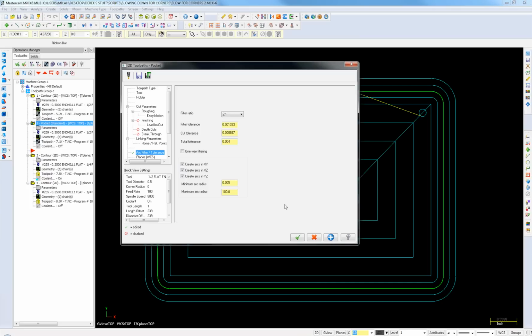It's really machine dependent and control dependent that makes a big difference. But if it's just an older machine without any look ahead at all, then you're usually always better to have the smallest amount of code with the most arcs that you can get. Right, Jay? Yep. Does make a difference. The machine moves a lot smoother, and will keep up with the speeds a lot better.